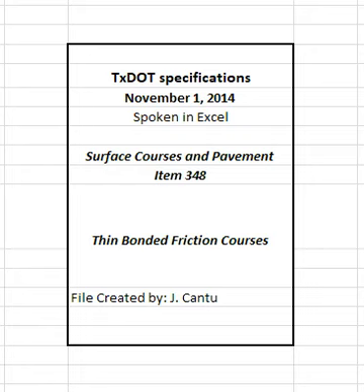When WMA is used, JMF1 may be designed and submitted to the engineer without including the WMA additive. When WMA is used, document the additive or process used and recommended rate on the JMF1 submittal. The engineer and the contractor will verify JMF1 based on plant-produced mixture from the trial batch unless otherwise approved.